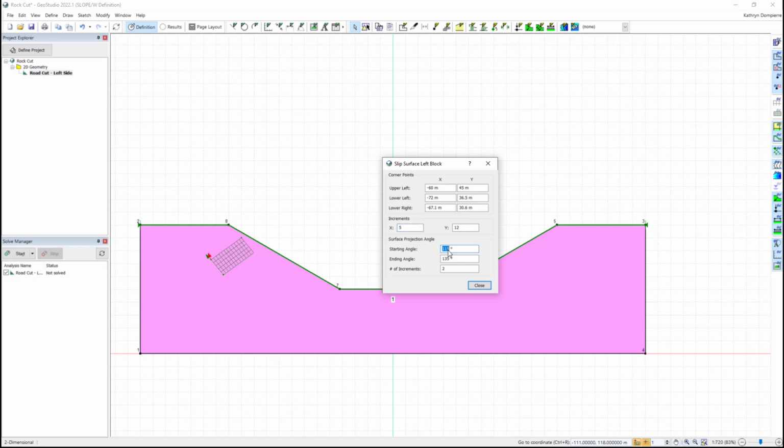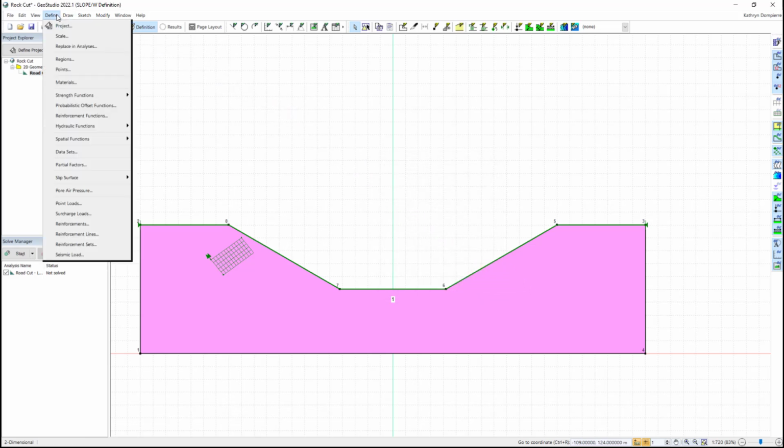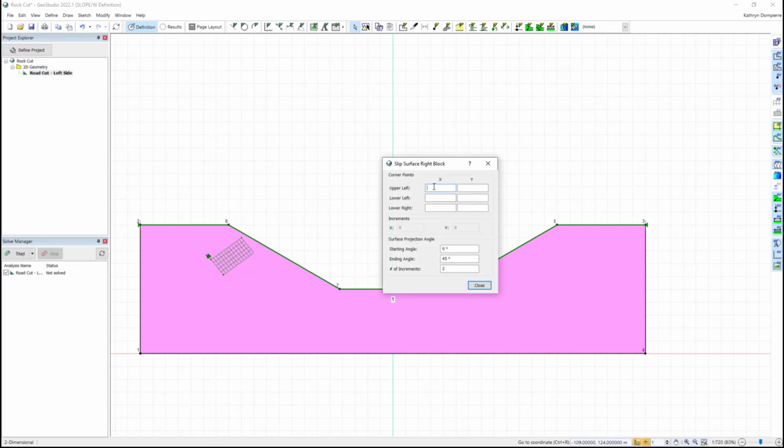We also specify the range of angles the slip surface should enter or exit each block. This allows us to force our trial slip surfaces to mobilize the resistance following particular orientations we wish to study, which in our case is the joint set's dip direction.